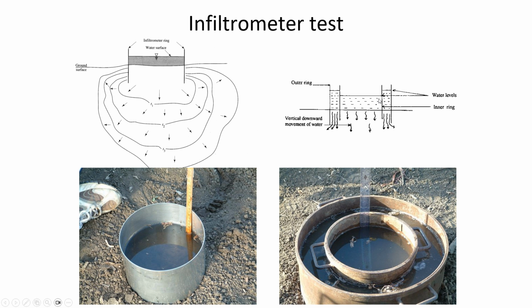So it's going to include both gravitational effects and also the suction effects. There is some amount of downward pressure because of hydrostatics, but usually they would only have a couple of inches of water, so it's not a great amount of excess pressure forcing water into the soil pores because of the pressure at the bottom of the ring. It's mainly going to be a function of the soil characteristics and the moisture content in the soil when the test is being performed.